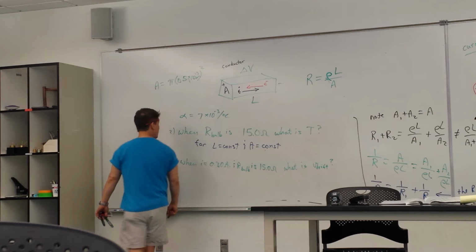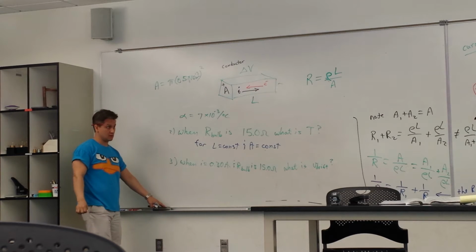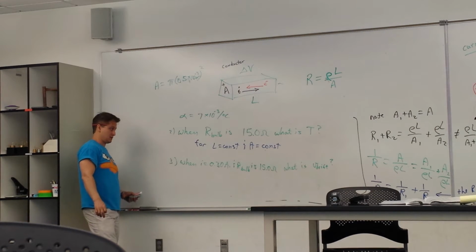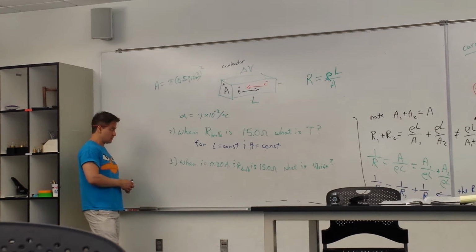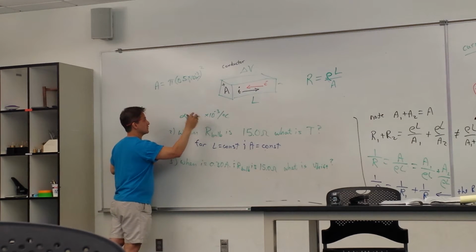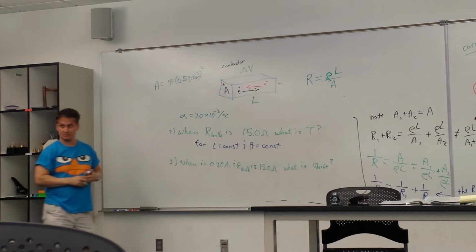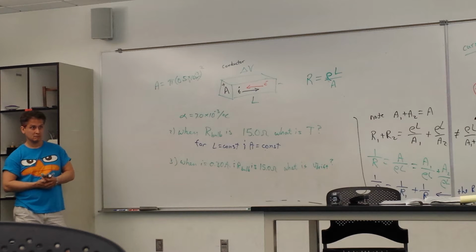So you get through that one and figure out the temperature. What's the drift velocity at that temperature? So what is our alpha value? 7.0 times 10 to the negative 3. Plus, not minus. You didn't? So you use a delta T of negative 10 times 10 to the negative 3? Who's got numbers to compare to my numbers?